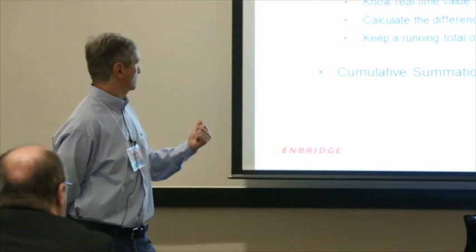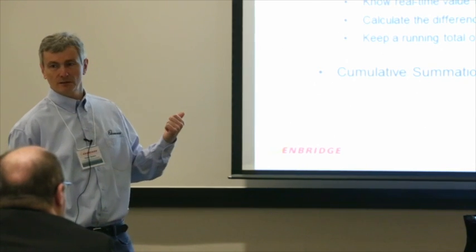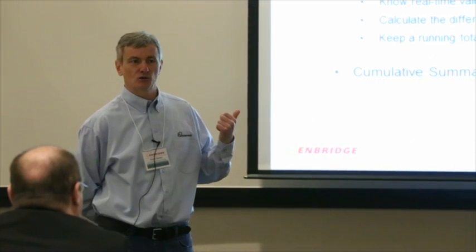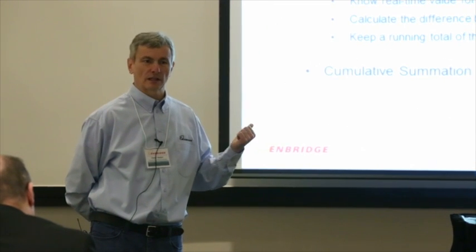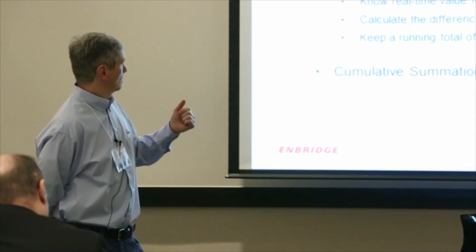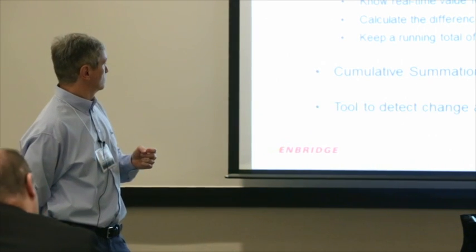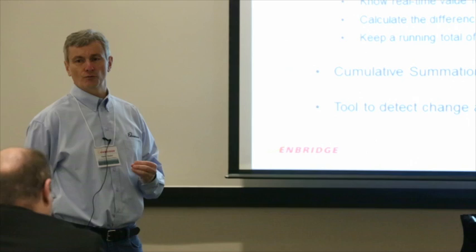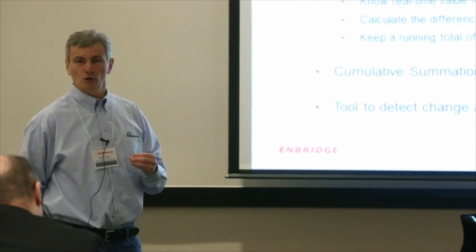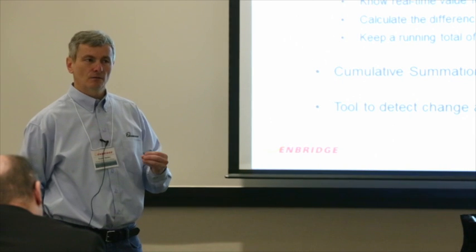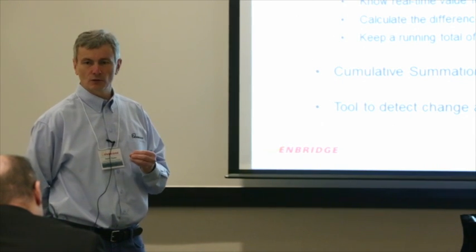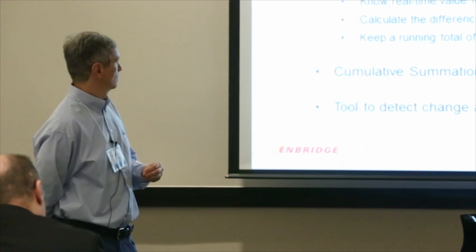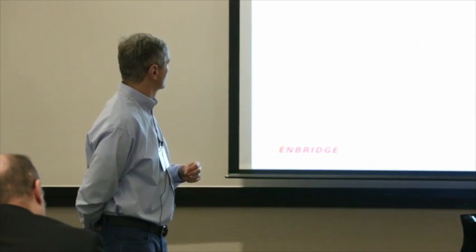mathematicians will call that cumulative summation of variances, or the famous Cusum graph that everybody in energy management has heard of or at least knows of. But that's essentially what it is. It's used to detect change and quantify the improvement. That's all Cusum is. It takes the difference between what's predicted and what's actual, and keeps a running total of that. That's all Cusum does. And how it works,